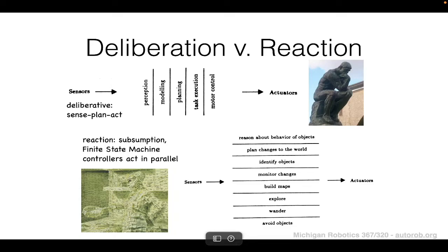You'll recall that deliberative processes typically follow a feed-forward process, right? You'll have sensor input from the world come in, you'll perceive that sensor input to form a perceived state of the world. You'll then plan very thoroughly across the possible actions that could be taken, and then finally you'll produce some actuator output in that process.